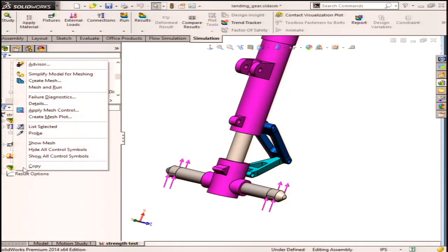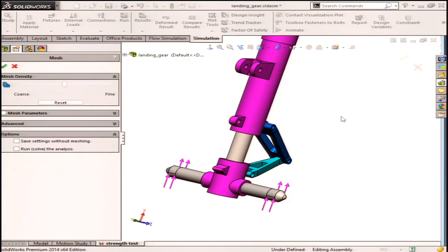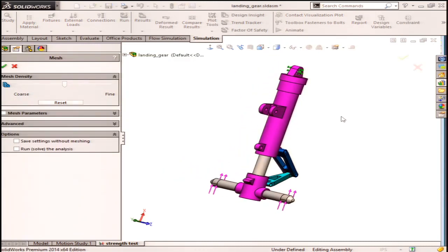Next we have our mesh. Now meshing, to me, in SolidWorks, using this auto mesher is probably my favorite feature of this tool. It can look like this, something very, very simple with this slider right there with it set to the center. And we can go to the left or to the right, sliding it, making it more coarse or more fine. And what we're doing there is we're defining the size of our mesh elements or the size of the measurements we're going to take. Now, you can leave this in the center because it's unique to every single model that you have. There's a function behind the scenes that predicts an appropriate size based on things like the volume and the